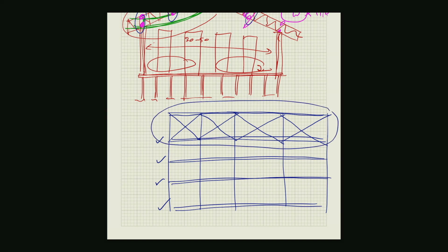This panel will be used for both wind, right? It is used to restrain the whole structure against the wind load, as the exposure area of the factory is quite a lot. So you need to restrain against the wind. That's the first thing. And the second thing is that this provides you stability. So the brace that you design has to account for two things.